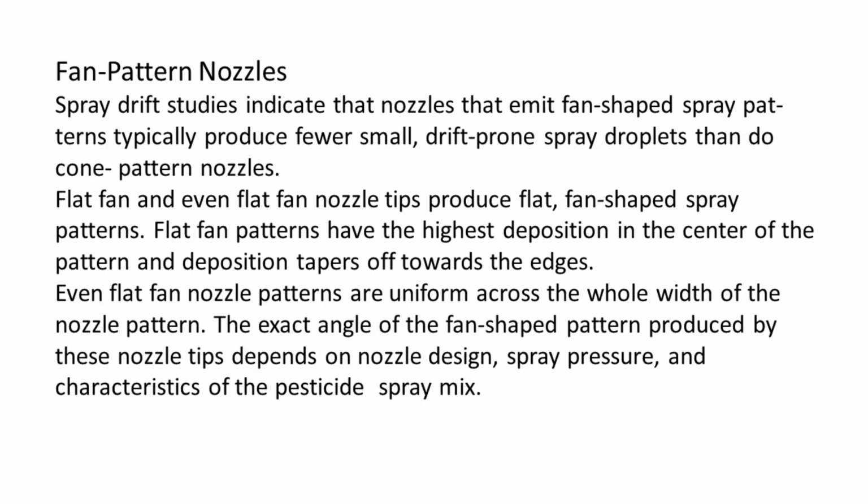Fan pattern nozzles. Spray drift studies indicate that nozzles that emit fan-shaped spray patterns typically produce fewer small, drift-prone spray droplets than do cone pattern nozzles. Flat fan and even flat fan nozzle tips produce flat, fan-shaped spray patterns. Flat fan patterns have the highest deposition in the center of the pattern, and deposition tapers off towards the edges. Even flat fan nozzle patterns are uniform across the whole width of the nozzle pattern.